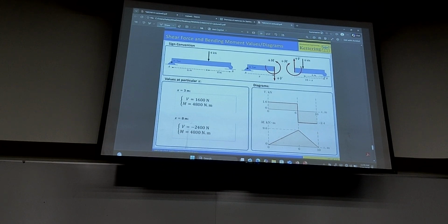If you're interested in shear force, and we said this is V and this is M, these two quantities, you break at a point somewhere in here, X apart. On the left segment, you put V downward and M counterclockwise. That's the convention, that's not my choice. And we put the opposite on the other side to balance it.